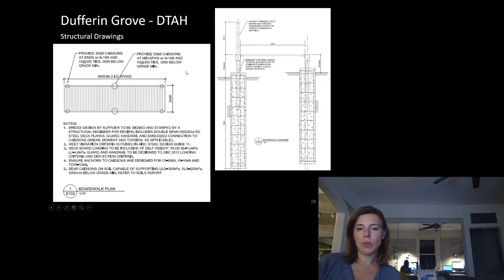It's the same premise when we're doing a stair. If we have outside stringers, people always say, well, what if we add a third one in the middle? Well, if these ones were too big, you're still just getting that big one in the middle, because that one is still taking half of the entire stair load.